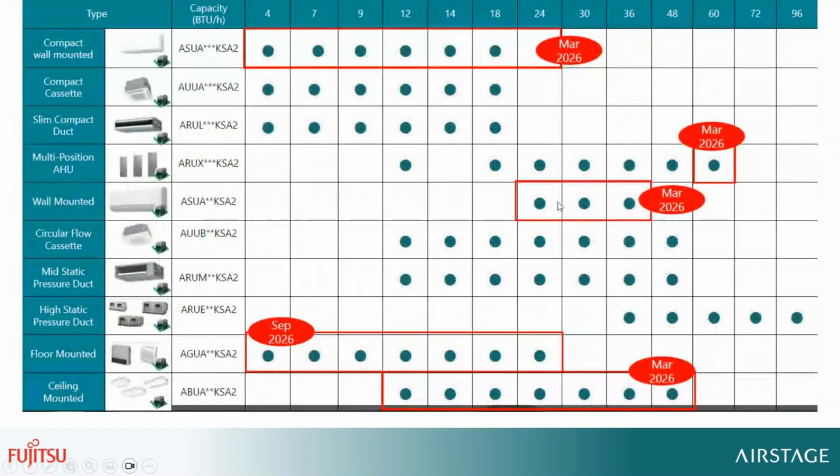Indoor units, this is a little bit of a busy slide, but the highlight here is every one of our new VRF indoor units that we'll have for R32 coming in next year in a few months will include a built-in refrigerant leak detection sensor. The current models that we have for the J7S, it's only the ducted models that include it. Whereas moving forward, our ducted as well as ductless, including wall mounts and ceiling cassettes, will already have a built-in leak detection sensor. So that should make designs a little bit easier as well.